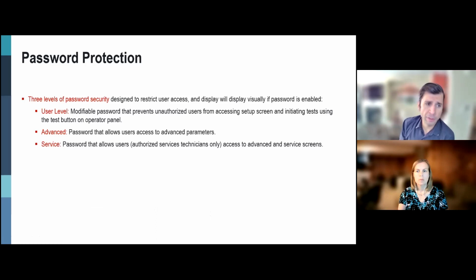You may also want different levels of protection, password protection in the control, so we don't have anybody messing around with the settings. You might have multiple levels: one level that has all the power, another level in between, say an operator, and then there's a user that we just want to let see the information and not mess around with any settings.